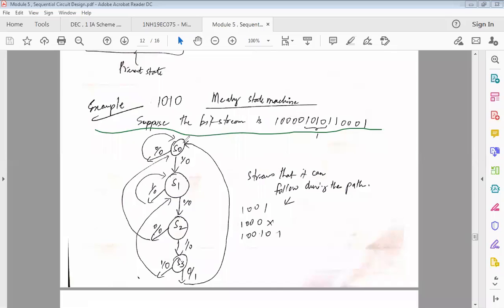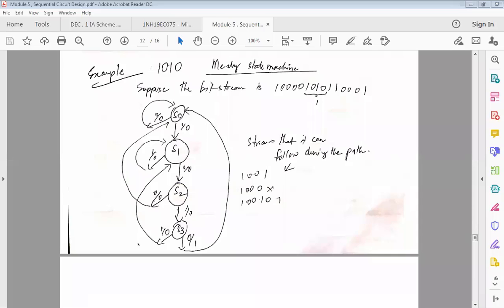Now, in the first case, you should understand that every state will have 2 cases, either 1 or 0, right? So what kind of model have I employed in this diagram? Is it Mealy or Moore? Mealy. Yes, it's a Mealy model, because I have input and output across, right? So the number of bits here corresponds to the number of states. I think all of you have understood this point. Here you can see the sequence has a number of states corresponding to the number of bits. Now that point is clear.